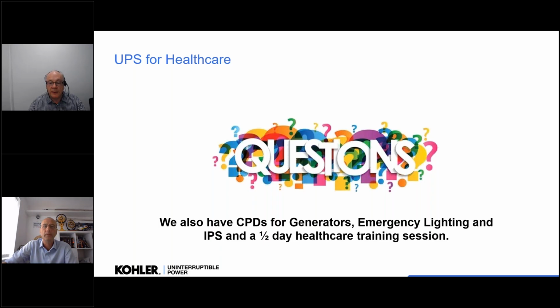Another attendee's asked, what are the primary differences between uninterruptible power supply and isolated power supply in the context of medical environments? The UPS, the uninterruptible power supply, is there to back up the critical load when the mains has a disturbance, either an outage, frequency disturbance, or a surge or a spike. Whereas a medical IT system, the IPS, is there to isolate the load from a neutral earth.